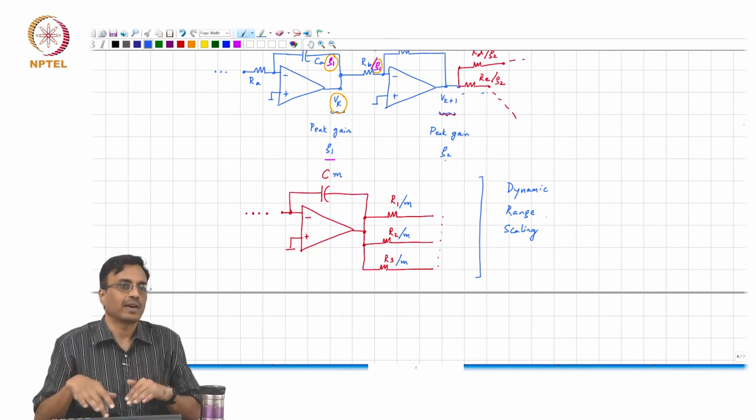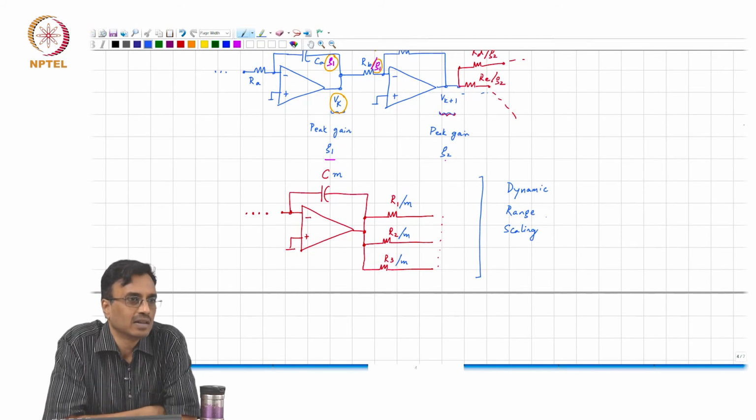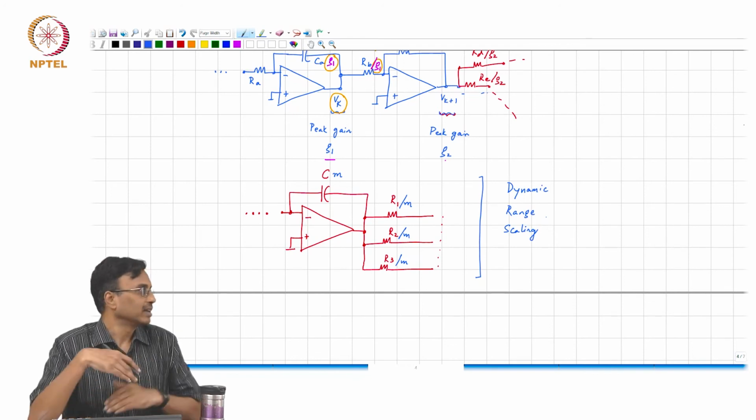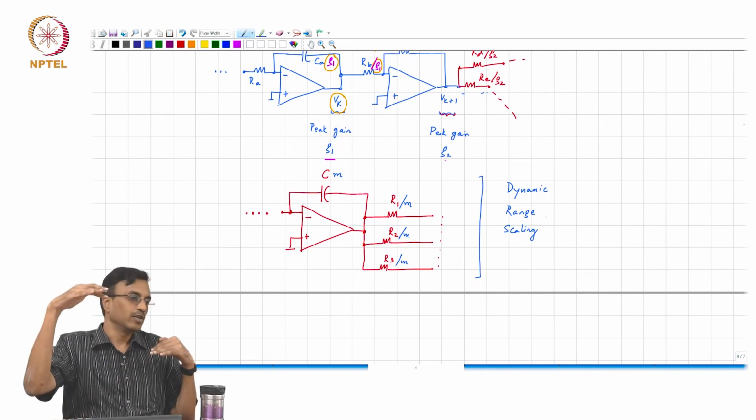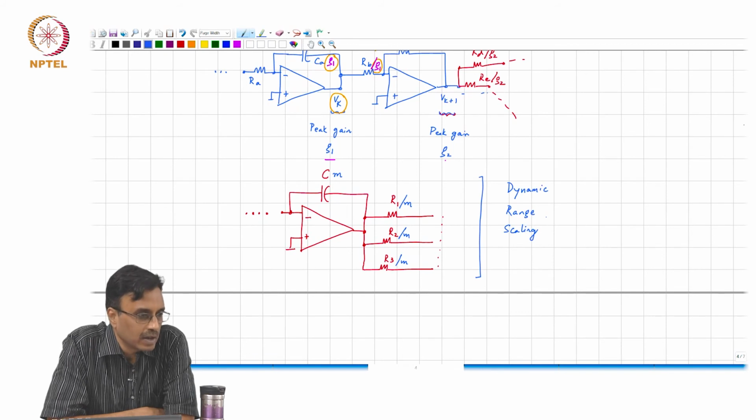So all the op amps hit saturation at Vsat, right, and the sinusoidal input that you can put in is, at least in principle, Vsat. This assumes that the op amp is all fine until you hit Vsat, and after that suddenly gives up, right. That's good enough for most purposes, right.